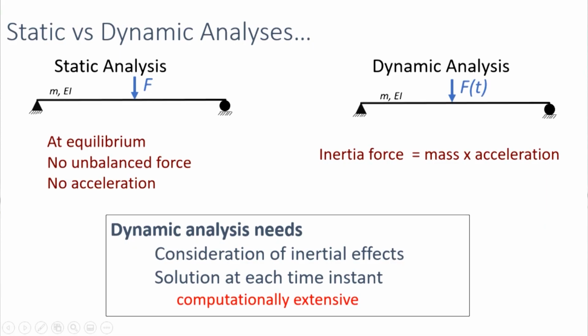So this makes dynamic analysis computationally extensive. We can say that dynamic analysis is an extension of static analysis. It is a generalized analysis, and static analysis can be treated as a special case with no inertia force or no time varying force.